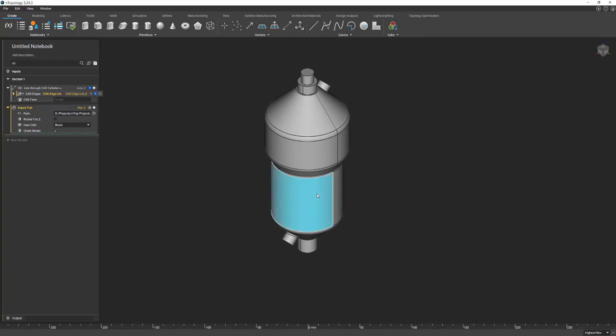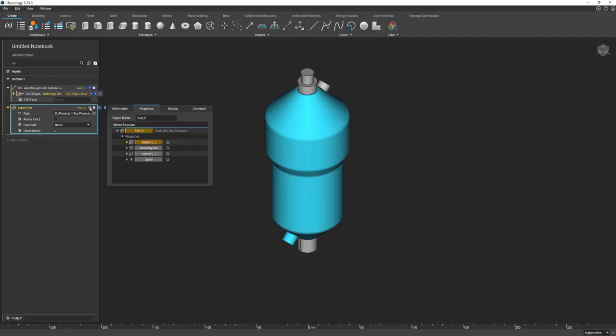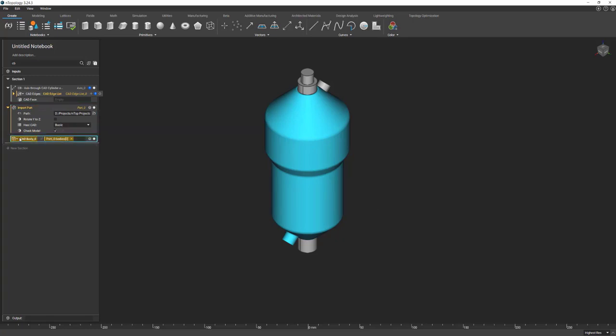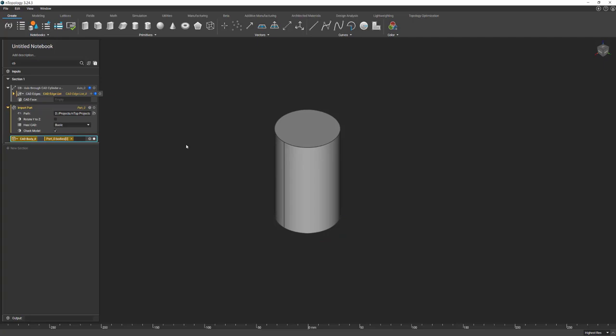As always, we can double click, right click, extract the CAD body, turn it into an implicit, access the different bodies under the properties panel, and pull out various entities and work from them. At the moment, I don't suggest bringing in assembly files and working with them. I'd encourage you to bring in individual part bodies.